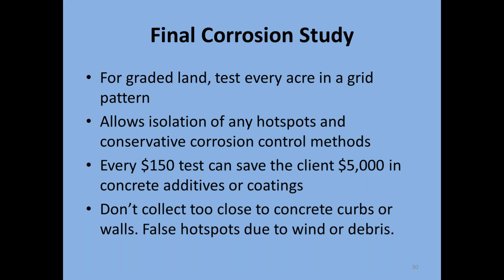So the other piece of advice, by the way, is I recommend you not collect soil samples close to concrete curbs or walls, because I believe the winds tend to collect a lot of things up against walls, and a lot of times we see hotspots at these locations, near walls, near concrete curbs.